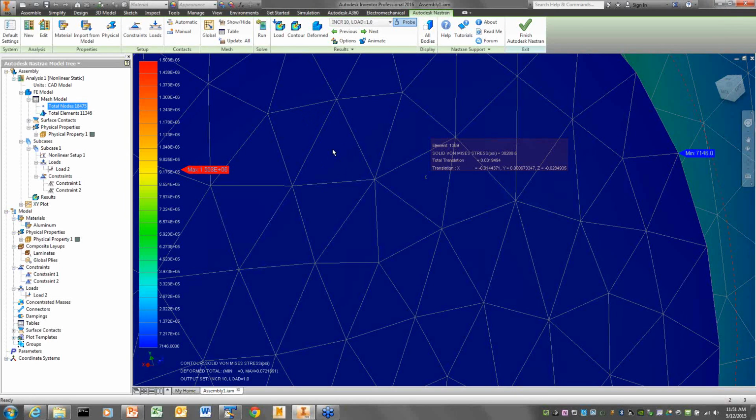So if I pick an element and ask for the force in it, it'll tell me it's 16. But that doesn't mean I've got 16 pounds in that element. It means the force in the direction it's calculated is 16 pounds per inch along the edge of it. So the forces for plate and solid elements are force per square or whatever. They're much harder to use element forces for three-dimensional elements.